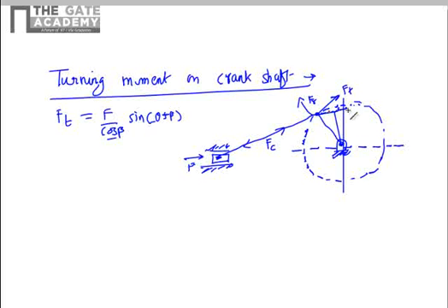That position we will term as D. And if you drop the perpendicular from the crank center O on this line AD, that point we will term as P, and the angle OAD is equal to beta plus theta that we saw earlier. Beta and theta are some of the internal angles of the triangles. So we know this quantity OD, and we will do a derivation where we will eliminate the use of theta and beta.